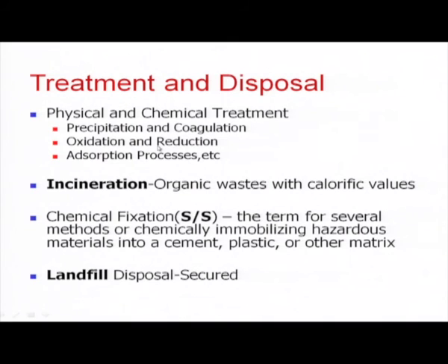Any metallic mercury that comes in should be converted into mercury sulfide, not a hydroxide, because in the leaching procedure TCLP we cannot meet the limit of mercury. So, only if it is stabilized with the sulfide, then it may meet the TCLP norms. Okay. So, this solidification, stabilization or chemical fixation is one of the important things before it is landfilled.